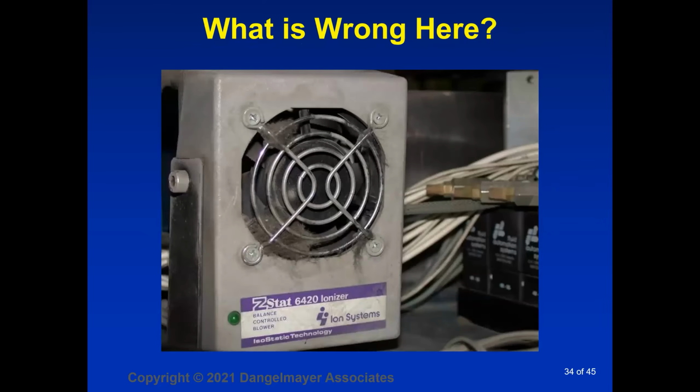Can you believe this? This is an unretouched photo, believe me. This is obviously an ionizer that has not had the maintenance it's supposed to have. It's interesting, the reason we found this ionizer, because it was tucked away behind some other equipment, was that we had an ESD event detector, and the ESD event detector kept going beep, beep, beep, because of the arcing that was going on inside this sad ionizer. So basically, you've got to have a maintenance program.